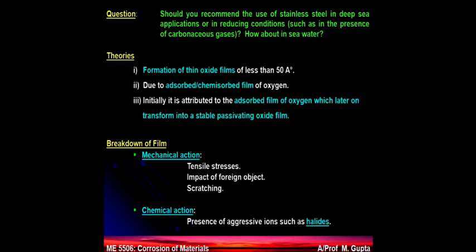So will the covered area become anode or cathode? It will become cathode. And the destroyed area where the film is destroyed makes an anode. And there will be very significant corrosion. The same thing happens in a power plant, because again the oxygen is limited, so the oxide layer of chromium oxide cannot heal itself. It cannot react with oxygen.